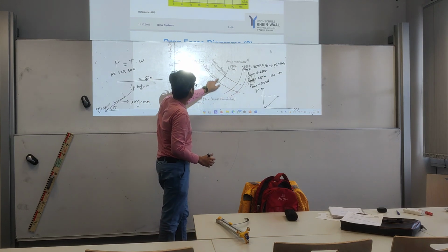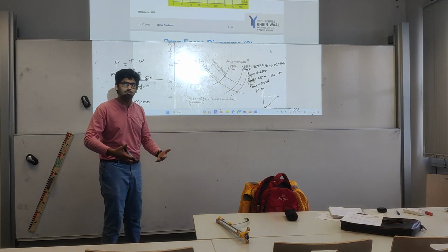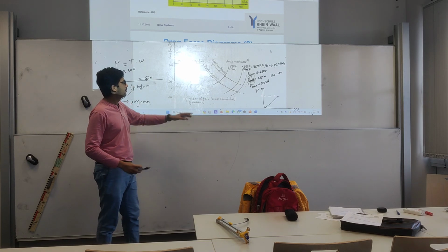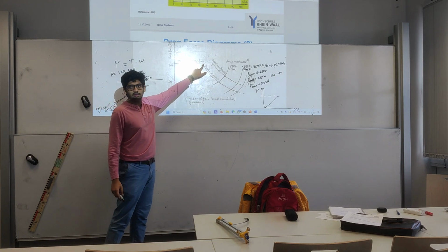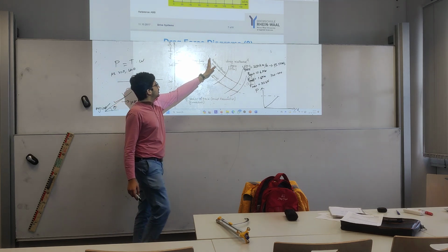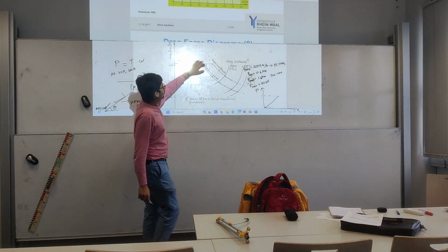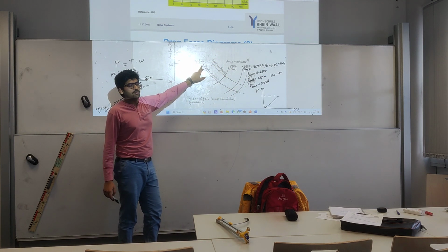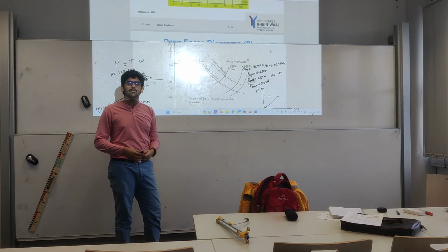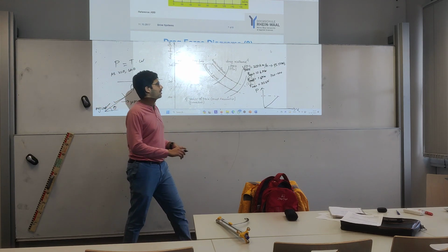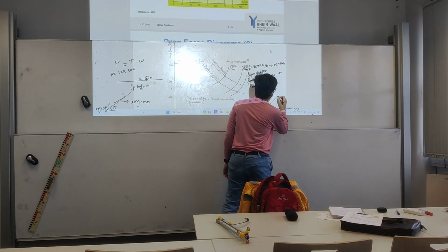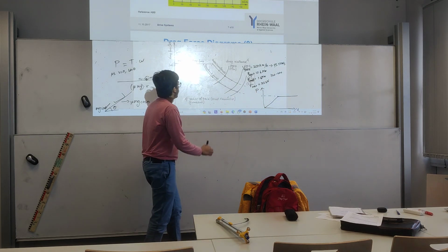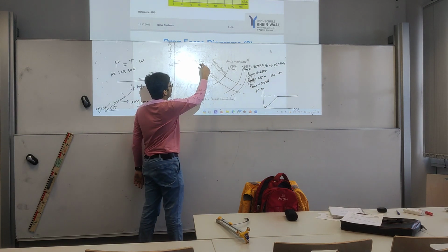Let's look at this constant power curve. Let's say you're running it at nominal operation, not overload or not for short time. So long time, you want to stop there because if you make, let's just imagine this part is not there. You cannot make any more power with the motor you have. So at this point, you have no choice but to decrease the torque. The torque comes down automatically because the power is limiting you and it stays like that. And that's why the torque is decreasing.